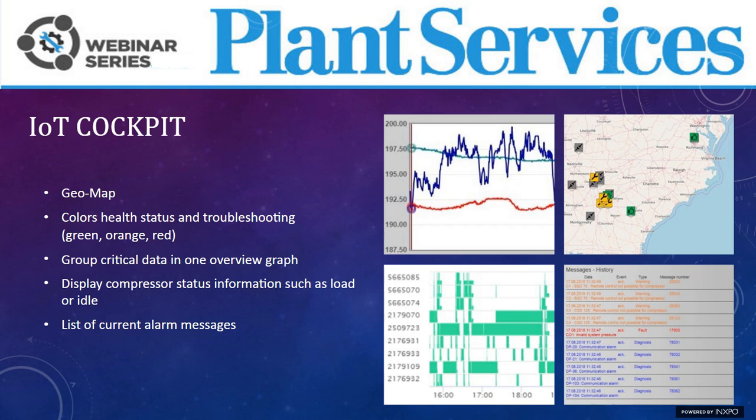Also, group critical data together in one overview. Take, for example, line discharge pressure or oil discharge pressure compared to temperature. And also here on the pictures, you see on the left bottom, display important compressor status information. I'd like to highlight load and idle. Keep an eye on that one as well. And list all current alarm messages. I also recommend listing all messages. It helps with troubleshooting and gives you a very good overview.